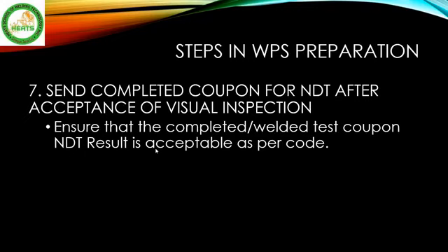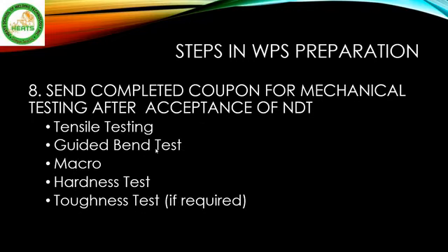So once the NDT result is acceptable, you can send the completed test coupon for mechanical testing. So you send for tensile test, guided bend test, macro, hardness test, toughness test if required. You send for mechanical testing in a laboratory.